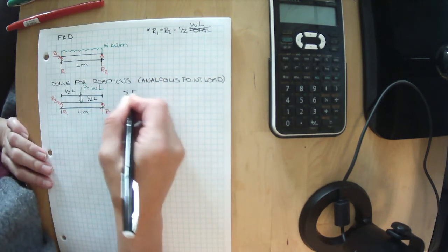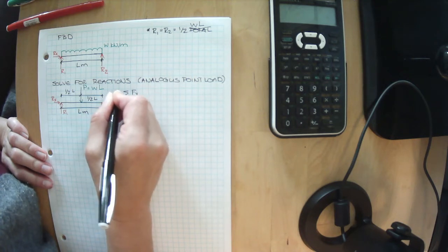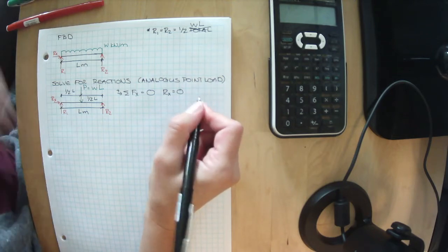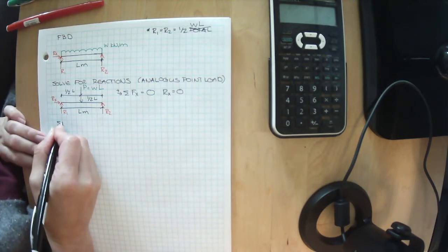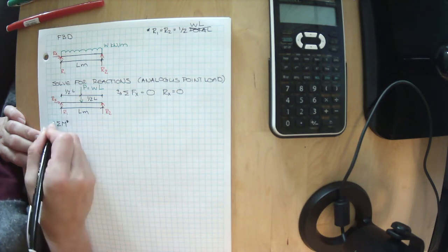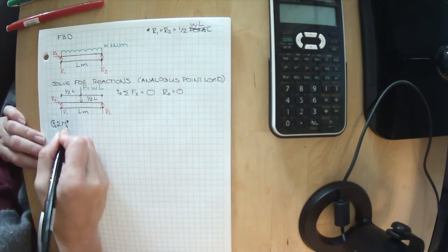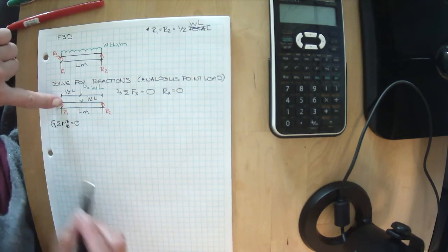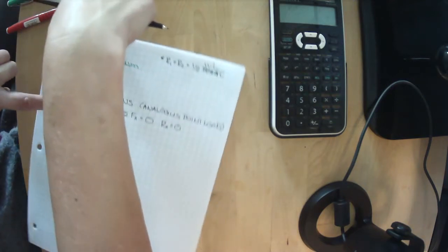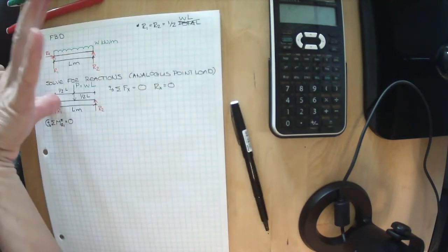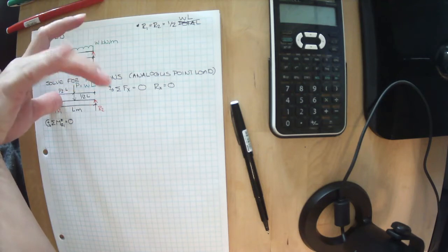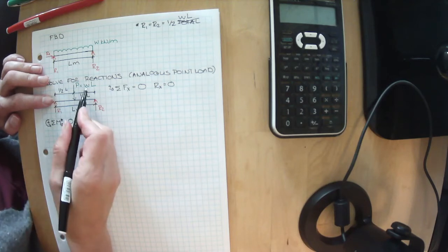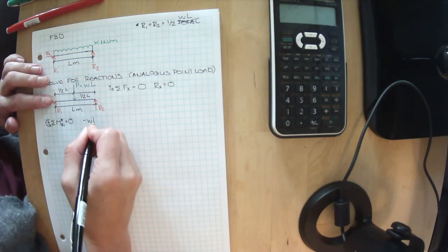So we sum the forces in the x direction. We get Rx equals 0. Let's sum the moments about the z axes where everything in that direction is positive, and I'm lazy. I'm going to pick R1 as where I spin my node about. We've got P spinning it in this direction, so we curl our fingers like that. P is a negative value, so minus P, but P is really WL.